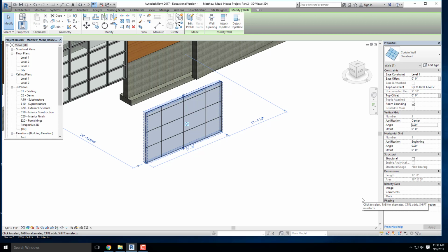So from the retail that I design, if I'm doing a retail storefront, let's say that piece of storefront is 12 feet, okay? Well, when I do retail storefront, I always have the top of that door at 7 feet, so it's going to go 7 feet, and then I might have two 2.5-foot module clerestory windows above that, okay? And then you might have your doors, etc. Okay? So let's look at how we might do that.